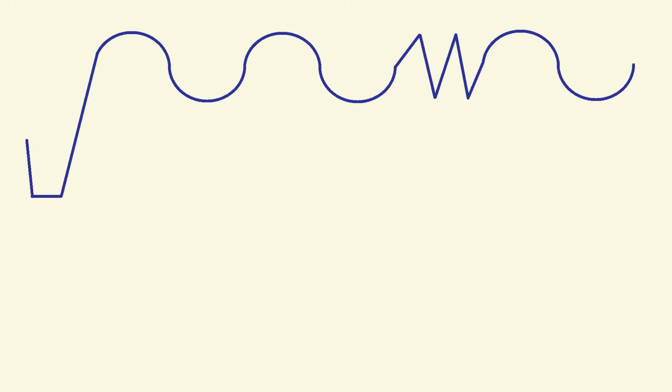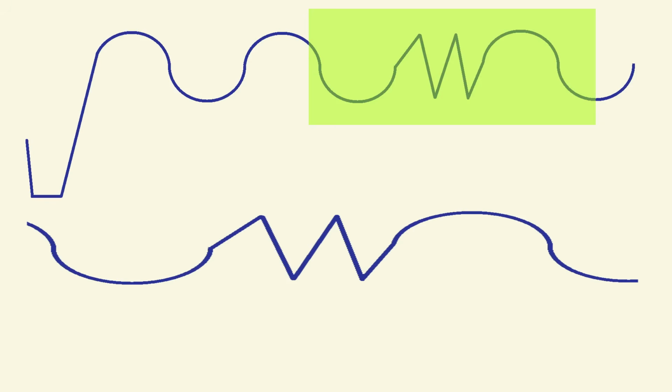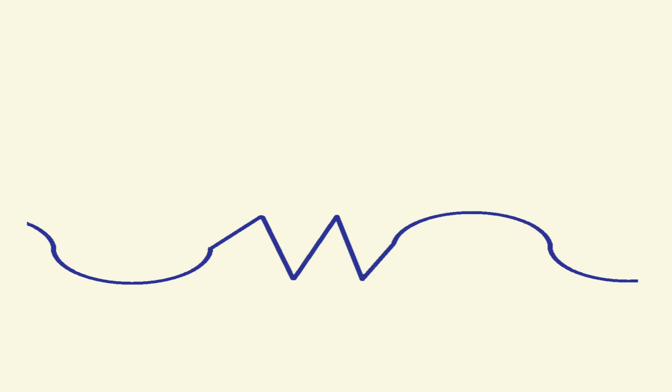Let's say that we have a signal like this, and that we want to zoom into something like this here. We can use the main time base to trigger on this right here. Then, using the delayed time base, we can choose this area and highlight it. Then, we can zoom into that section, and we can then remove this longer signal from the display if we want. Let's look at how to do this on the scope.